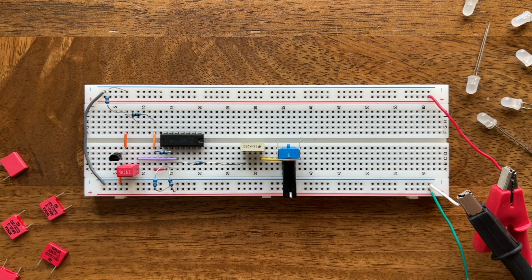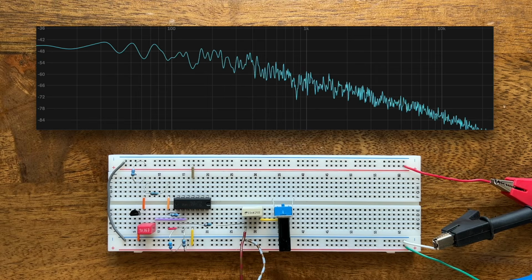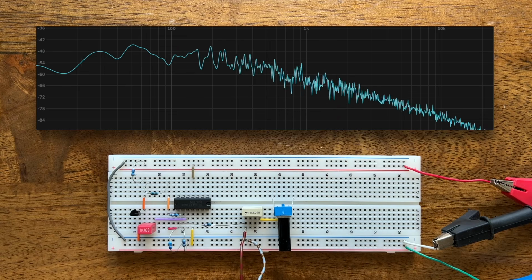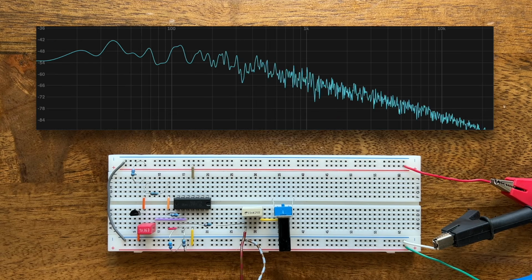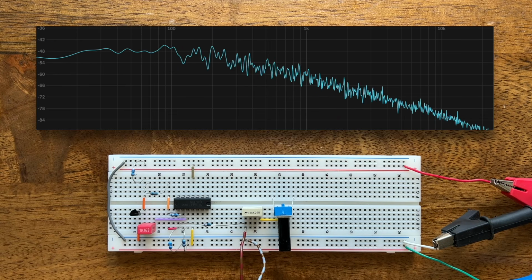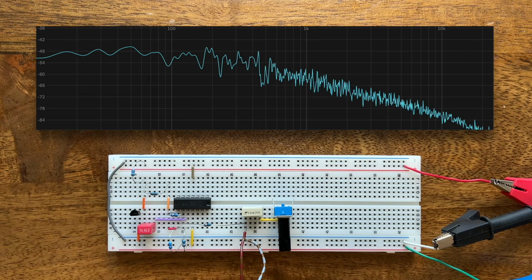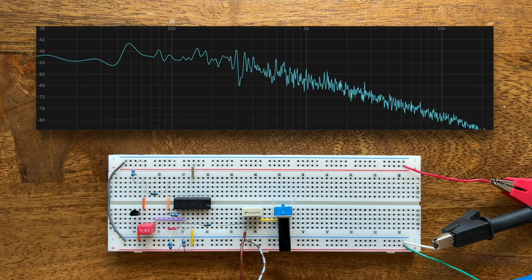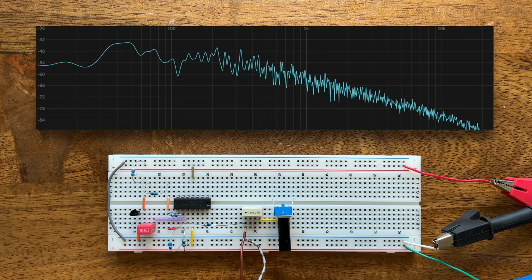But instead of a square wave oscillation, we're using the white noise signal as an input. This will make it much easier to visualize the shelf filter's effect, because white noise, as we discussed earlier, contains all frequencies in equal amplitude. Usually, I show you output signals like these with my oscilloscope. But in this case, it's actually much more helpful to use a spectrum analyzer instead. This way, we can see which frequencies are present in our signal, and at what volume.